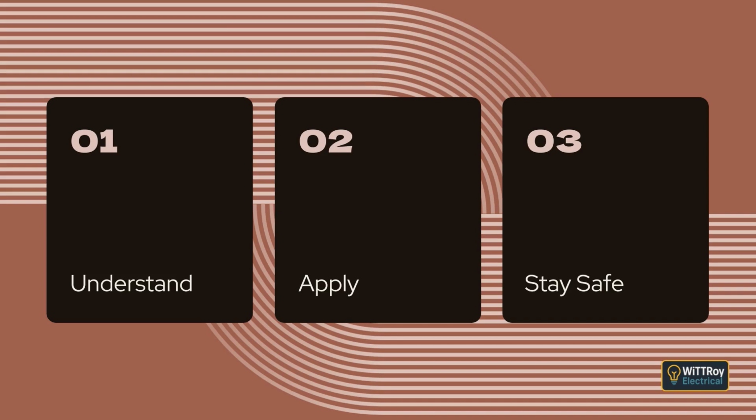Clause 2.5.7.1, General. Clause 2.5.7.1 repeats the key idea in a simple way. The installation must be arranged so supply is reliable. That reliability is achieved by dividing the wiring into suitable circuits and choosing protective devices that will operate in the right sequence. The goal is that when a protective device trips, it affects the smallest area possible. Only the faulty part goes off, and all the other parts continue supplying power. Again, the settings must be inspected to ensure the protective devices are coordinated properly.